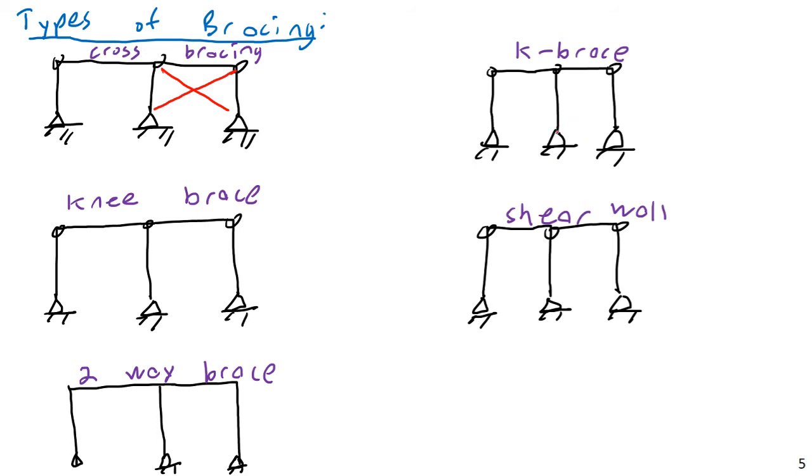K-brace still takes up a lot of space, but gives you a little more room. It's going to be something like this. So you have a K coming in at 2 in one direction. Now I've seen you can have K-braces like this, or like this if they're across 2 floors or something. But the K-brace basically at one point is going to meet at the middle of a frame, and in the other dimension it's going to meet at the ends of the frames.